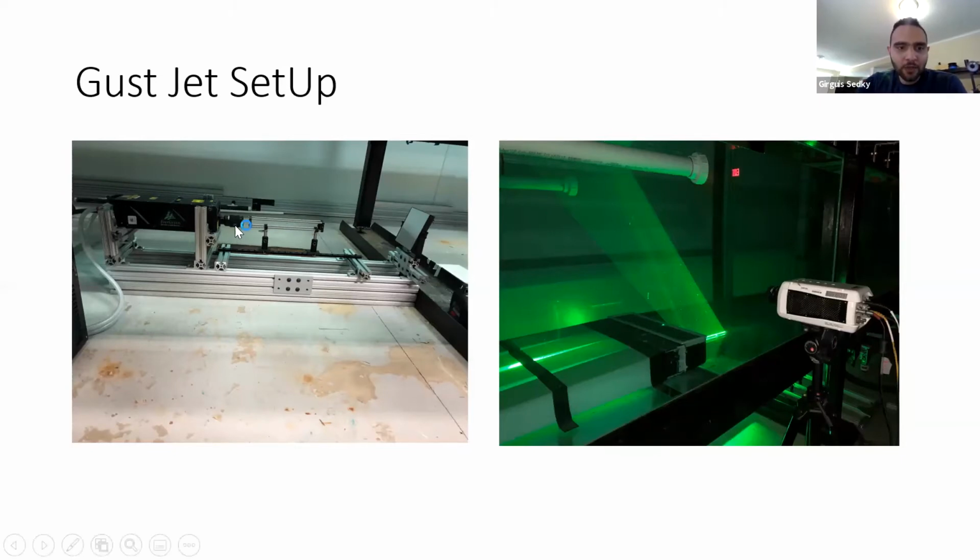Anyway, so you have this telescopic lens shooting the beam down. The Powell lens is right here. The laser beam comes in this way and fans out to a laser sheet. The laser sheet hits the mirror, and the mirror reflects the laser sheet upward into the tank, which you can see here. So this is the laser sheet. And then you have the camera here.